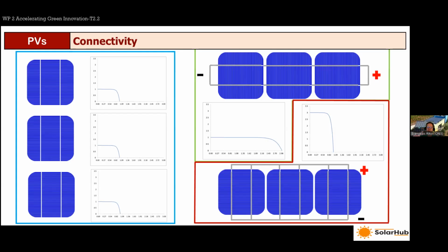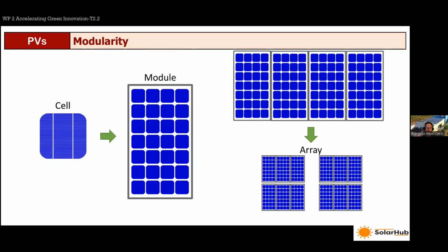So what we usually see in commercial photovoltaic modules is PV cells in series connection, mostly. But of course, parallel connection could be the case, especially when we go on to combining modules, for example, to increase the power of the system. And we'll see about it in one of the next slides.